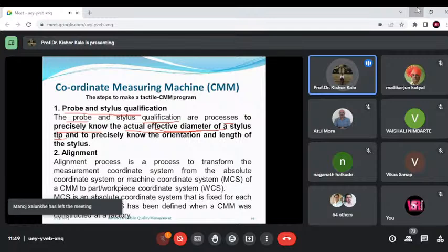So we have to find out the transformation, how to move this to this. It is not only a movement. You have to lock all 6 degrees of freedom. That means 3 rotations and 3 linear motions have to be done so that it exactly matches with this. For that we have to define which are the best 3 different points for XY. We have to define this CRF and IRF. So you can see they are aligned in this figure.